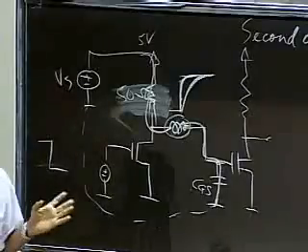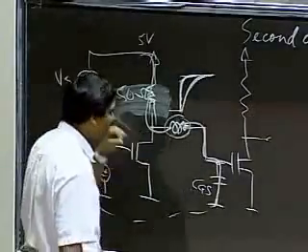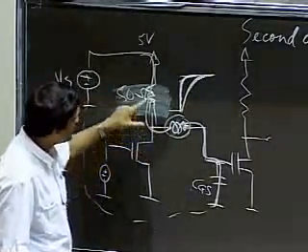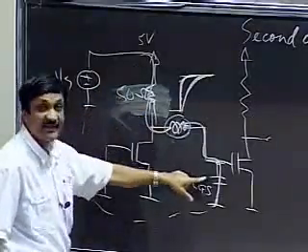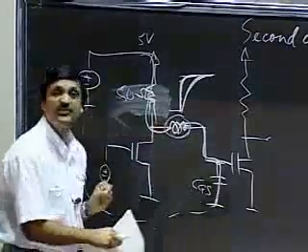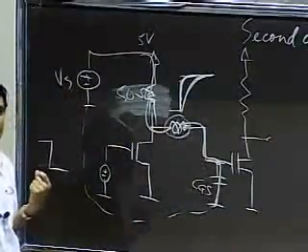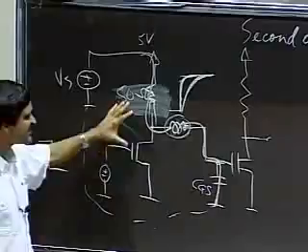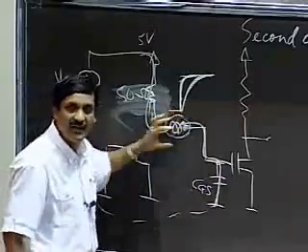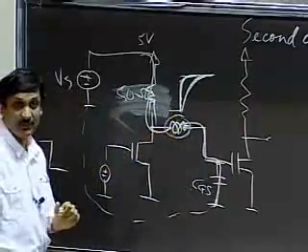Every wire, when there's a current flow, has an inductance associated with it. And because of that, the real circuit is resistor, inductor, and capacitor. Okay, so I end up with two storage elements now. And the dynamics of that are very different from that with a single storage element. So that's just a bit of motivation for why our study of inductors is important.